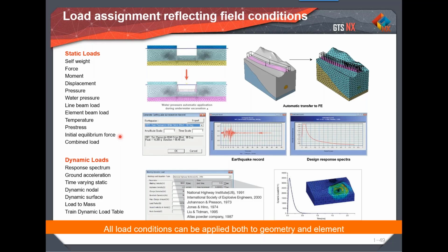But let's say you're dealing with rocks which have huge in situ stresses. In that case you can go for initial equilibrium force. You can simply input the stress that you calculate or get from the investigation team, and you can directly apply the initial stress that is present in the soil or rock, and then go for the analysis accordingly.